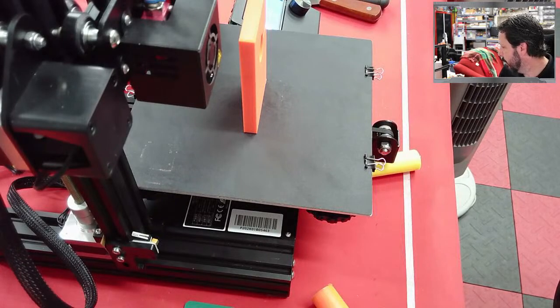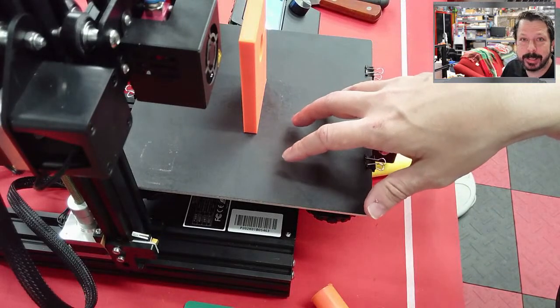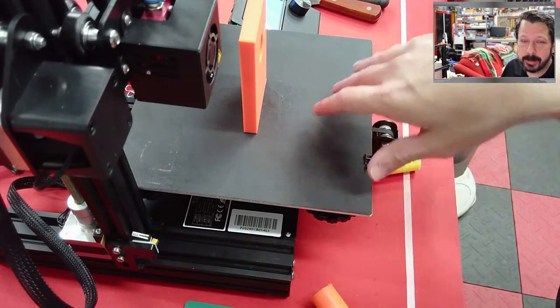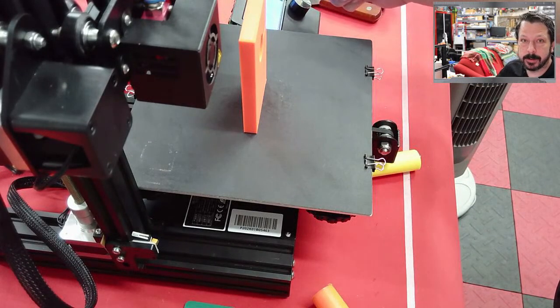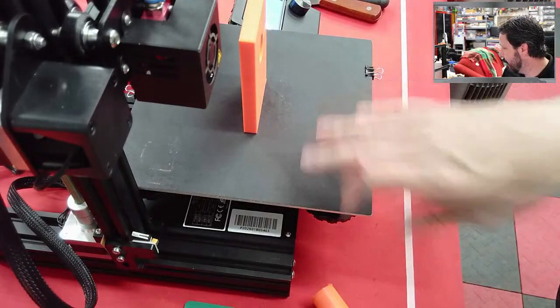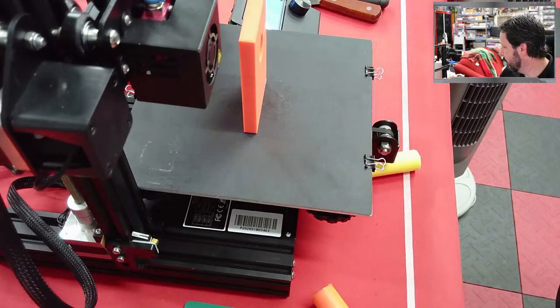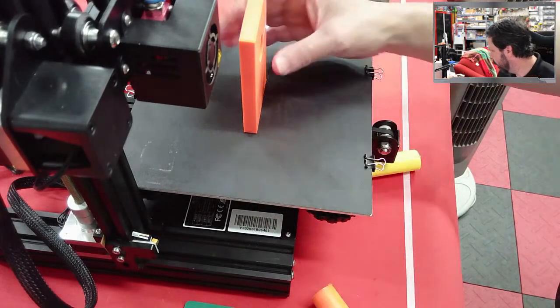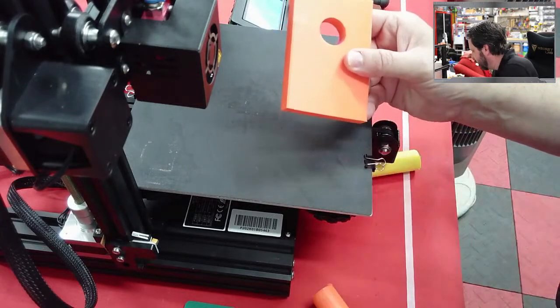You can go in and tape it back down to your bed as it's printing. Maybe you have to pause the print to get it on there, but you can pause it through the control panel on the printer and tape the part back down if you don't want to start over. A lot of times you've already invested 30 or so minutes, and you think you can save the print. Now this one, it saved itself. It didn't actually fail, but this corner back here is slightly raised up.